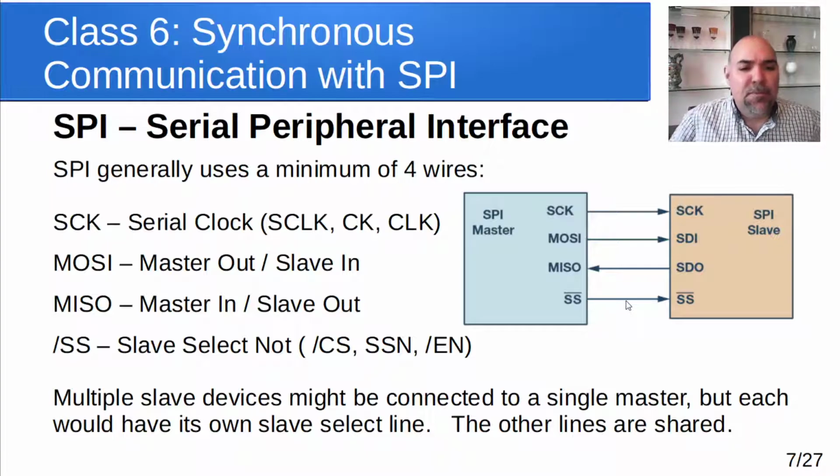Now, sometimes slave select will be labeled SSN for slave select not, or /CS, which stands for chip select, or /EN for enable. But they all kind of do the same thing. They activate the device, allow it to wake up and do its thing.